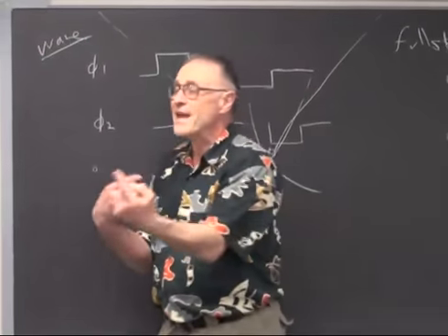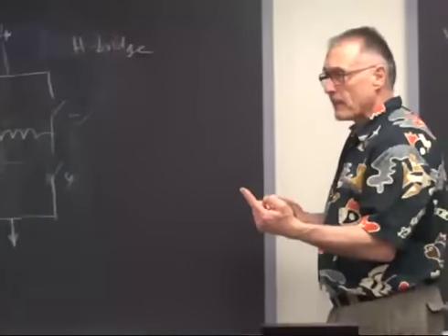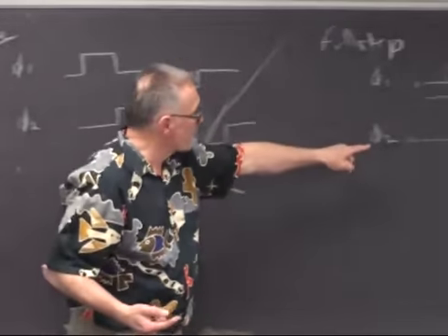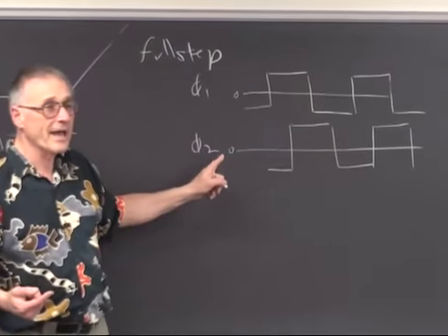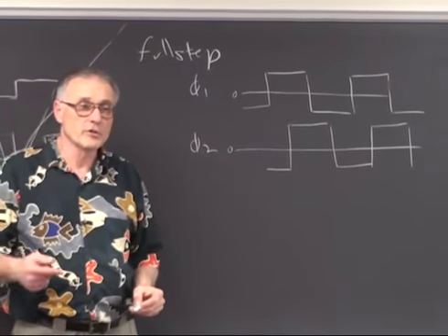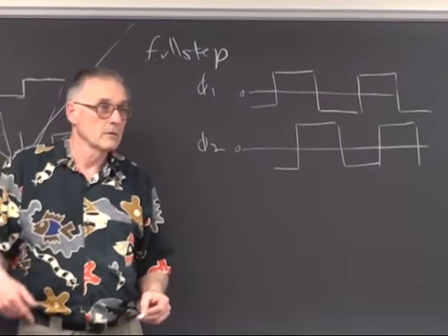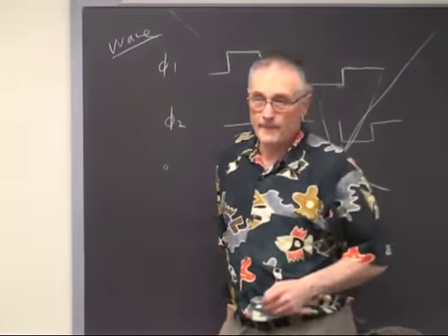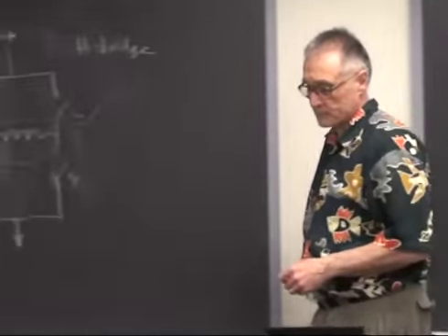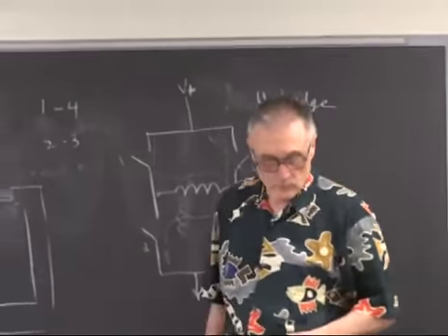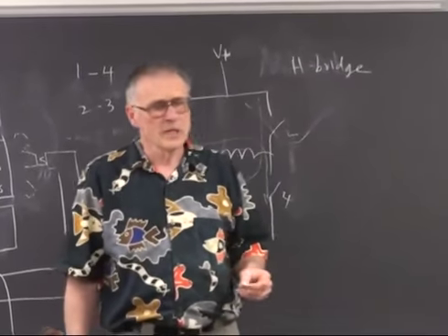You set the phase of phase 2 either 90 degrees leading or 90 degrees lagging, and you will have motion either clockwise or counterclockwise. Any questions about that?